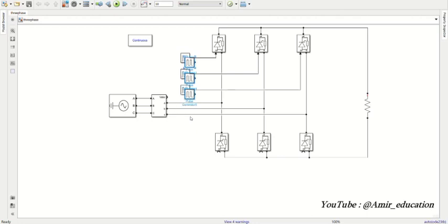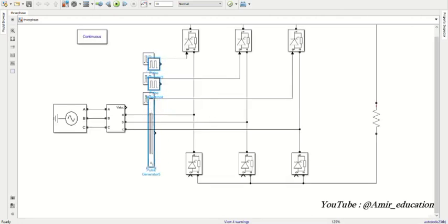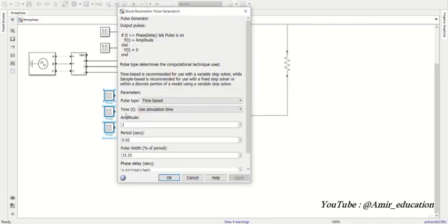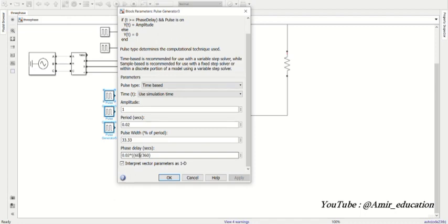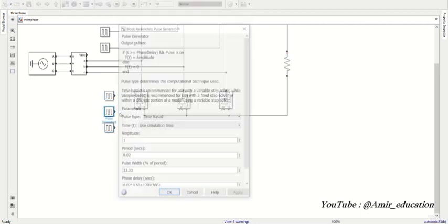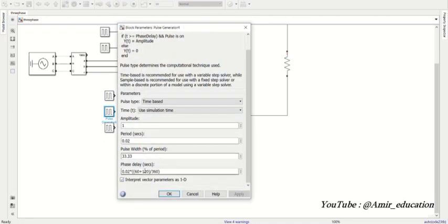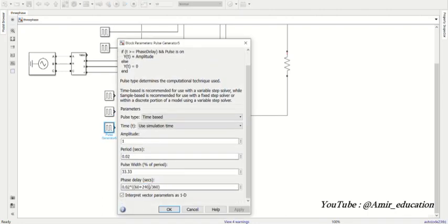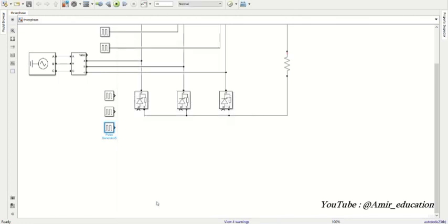And for the thyristors beneath, here we should delay by 180 degrees because with this differential we have the best situation to inject the least THD and harmonics into our network. So they'll have a difference of 180 degrees with the upper thyristors.